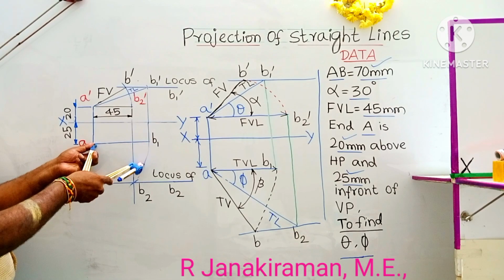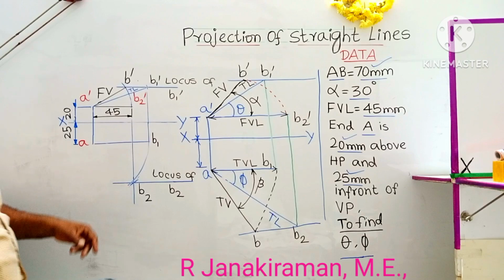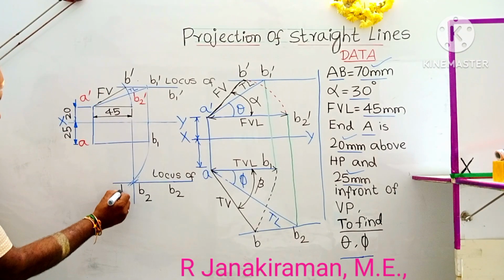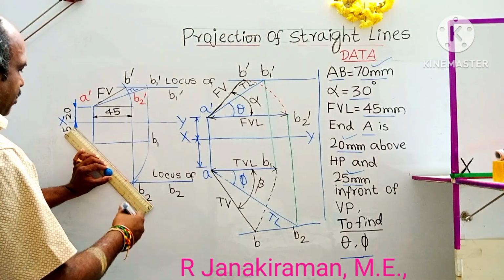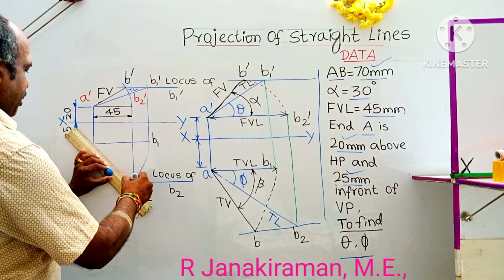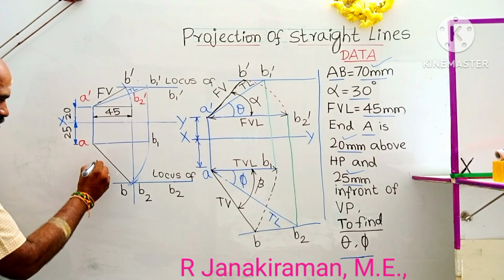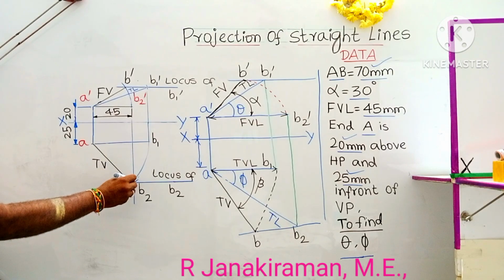Draw an arc downward. Where this arc intersects with the horizontal line, that point of intersection shall be marked as B. Join AB. This is the final top view obtained, drawn with an HB or H pencil so it appears dark. This is the top view, written as TV, and AB2 is already marked.